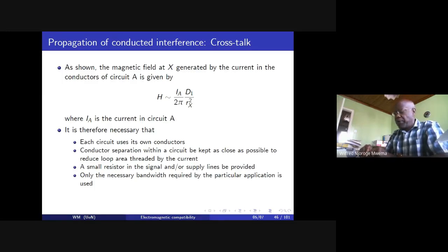Well, the digital circuit engineers are right. Of course, you need a very sharp edge because sometimes you may not be able to recognize what is a pulse or a level 0 or a high level or a low level. But what we are saying is, in terms of EMI, use as fast a rise time or a fall time as is necessary for the function to give you the required or the desired application, rather than making it better than it should be.